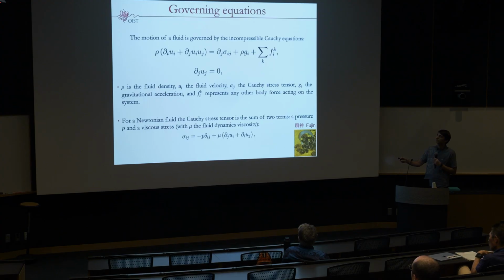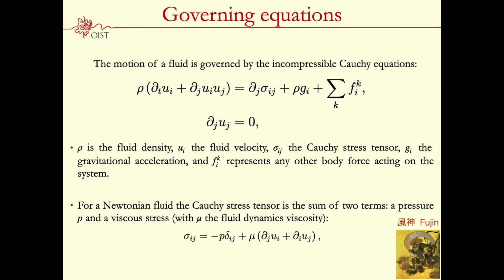We have 1 equation for the evolution of the velocity of the water or air, whatever you are considering. And this equation, we have a time derivative, is nonlinear. And then there are some terms on the right-hand side. We have two unknowns, the velocity and the pressure. The velocity, we are in a three-dimensional world, so it has three components. The pressure is a scalar, so we need four equations. There is one extra equation, it's just a constraint in this case, which makes the flow incompressible.